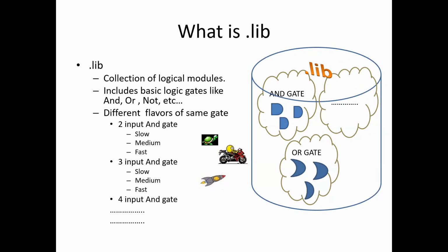Say for example, we know that a NAND or a NOR can implement any logic function. So if I just have a NAND gate and NOR gate itself, that's more than sufficient for me to implement any Boolean logic function because NAND and NOR are universal. Correct? So .lib contains standard cells to implement any Boolean logic functionalities.